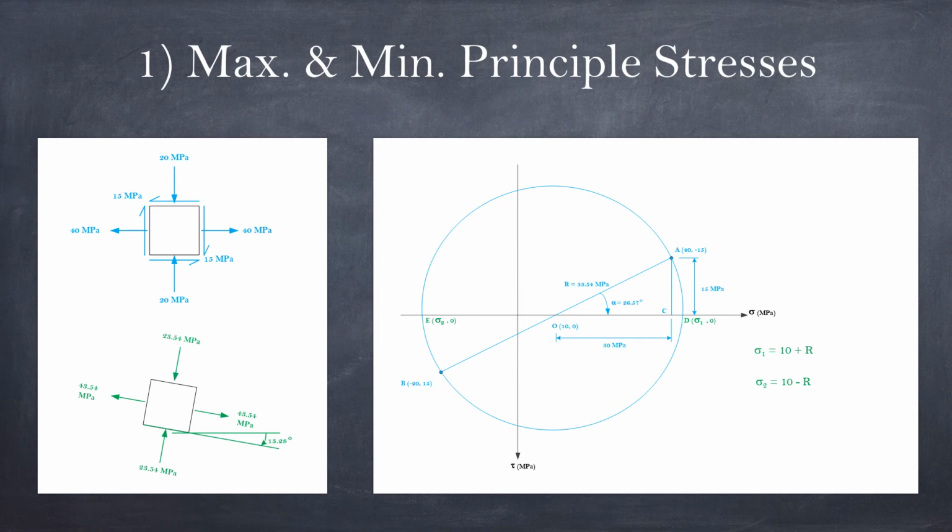When we look at the maximum and minimum principal stress, I did not actually get into detail because it's quite a simple calculation. What happened is that, remember the blue line. The blue line is the original sigma x, tau xy, and then sigma y, and then tau xy, right? Then if we want to go to the maximum principal stress, we have to rotate these two lines until they match the horizontal line, correct? Meaning you have to turn this line clockwise by 26 something degrees that we already discussed, right? Then we have sigma 1.